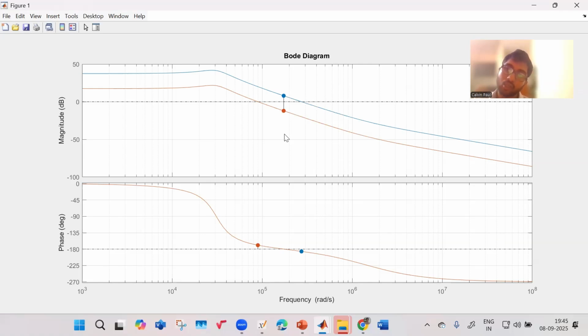That's what we told you, loop gain analysis. You will adjust the loop in such a way that the phase margin will be 60 degree, 30 degree, what you want. And your crossover frequency is also designed for a higher value, so that your response will be fast.